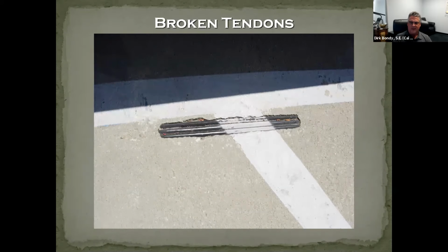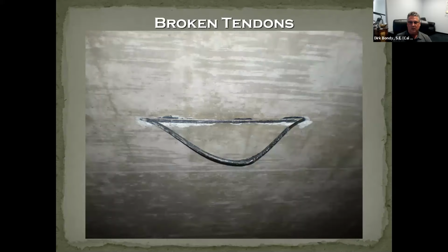So clearly that didn't happen within the last week. The tendons may pop out of the bottom. Again, they're going to usually find the location where there is the least amount of cover. The path of least resistance will be where the tendons come out, but you may have to follow that tendon line for 50 feet or 100 feet.